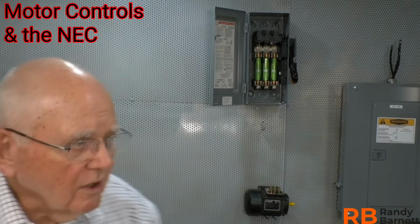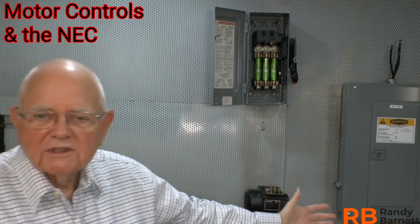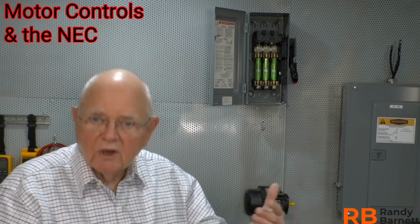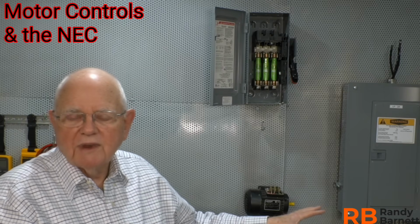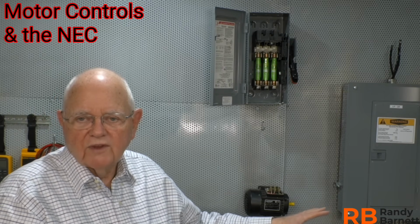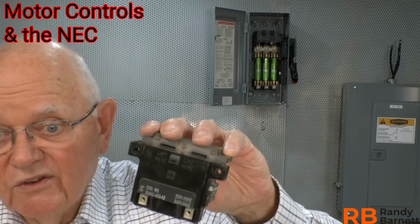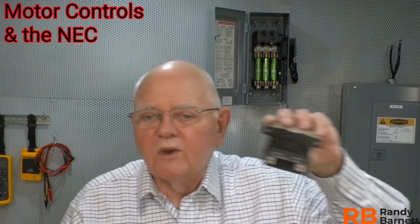So for my motor, what am I drawing on a 10-horse motor? The code book tells me it's 14 amps. I don't care what the nameplate says. The code book, when I size these conductors, says that's a 14 amp motor: 10 horsepower, 460 volts, 3-phase. The coil only draws 2 amps. So I probably don't need those same 10 AWG or 12, whatever it is.